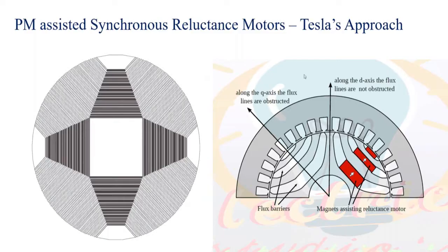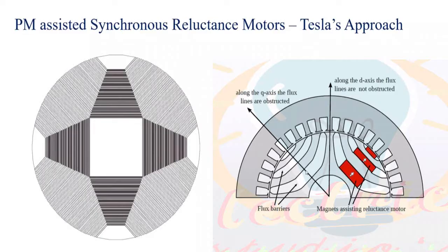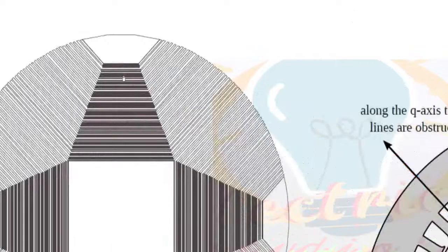If I don't want to use the permanent magnet, then in the synchronous reluctance motor, the rotor design has to be modified. You can see totally 3 barriers here, 1 through 3, for the flux to flow. And look at this picture. This is a rotor designed by a researcher in Australia, with these many barriers. Can you imagine this many barriers being designed on the rotor? Here only 3, but here there are multiple barriers.